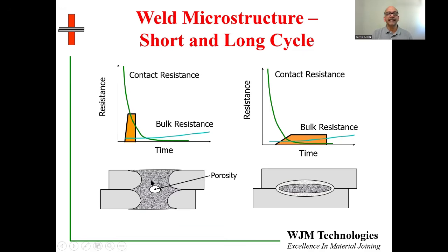And what we will see is the heat affected zone, or sometimes even the fusion zone, extends all the way from the top surface to the bottom surface. Another interesting feature that might show up in some of these welds is the formation of a porosity in the middle of the weld.